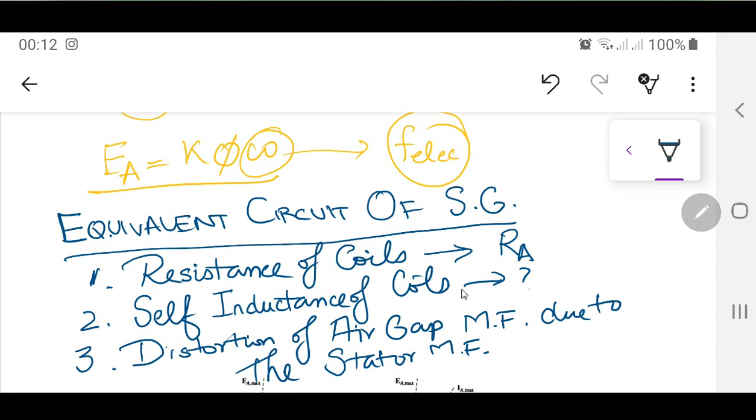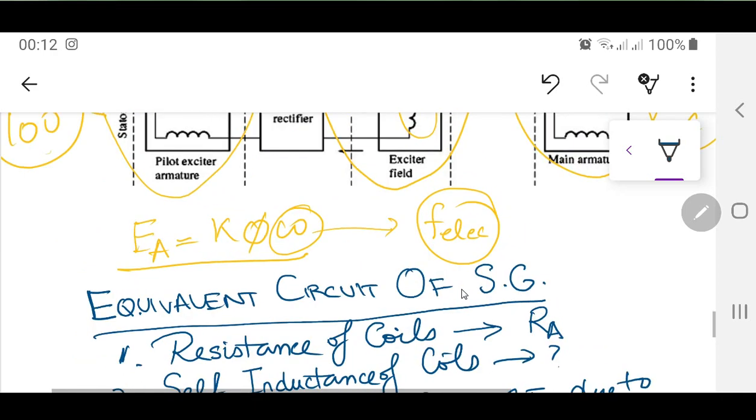If you remember your DC machine, there was an armature reaction, and that armature reaction was changing the orientation of the magnetic field direction. The magnetic neutral axis was changed. This time, since the stator has a three-phase winding, and that three-phase winding is going to be producing an EMF, and you are going to connect it to some load, there is going to be a current flowing through that A, B and C phase.